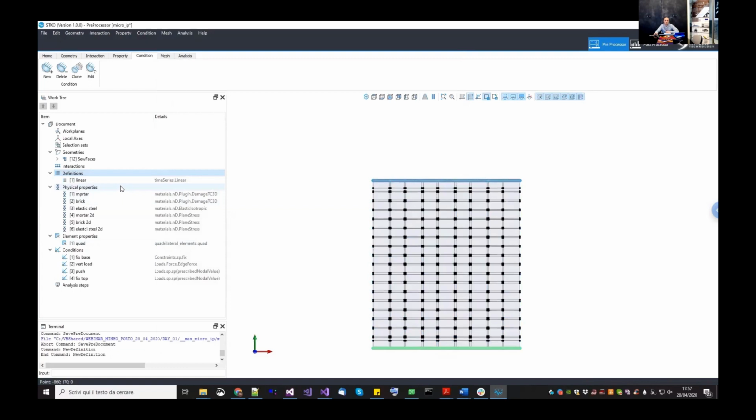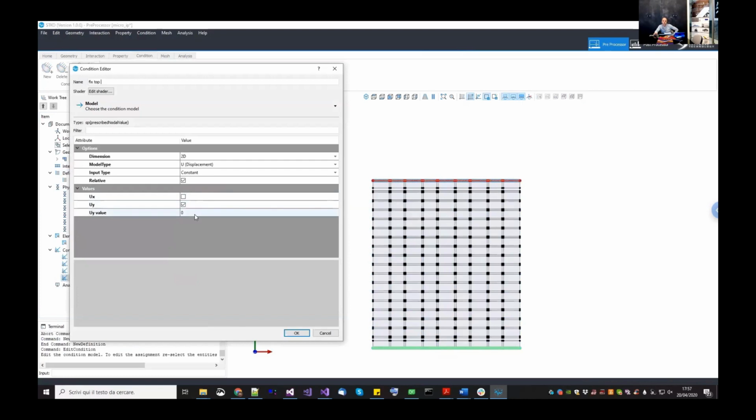But then we need another, different time series for the prescribed displacement in the y direction. Even if we put 0, which is a constant, you may say you don't need a load multiplier because it is 0, so you can multiply it by whatever number. No, it is not actually 0. Here it is 0, but in the Tcl code, it will become 0 plus the current displacement. So it is actually a value. If we multiply with an increasing time series, let's say it will be 0 plus 10, because it moved 10 millimeters, it will be applied from 0 to 10.